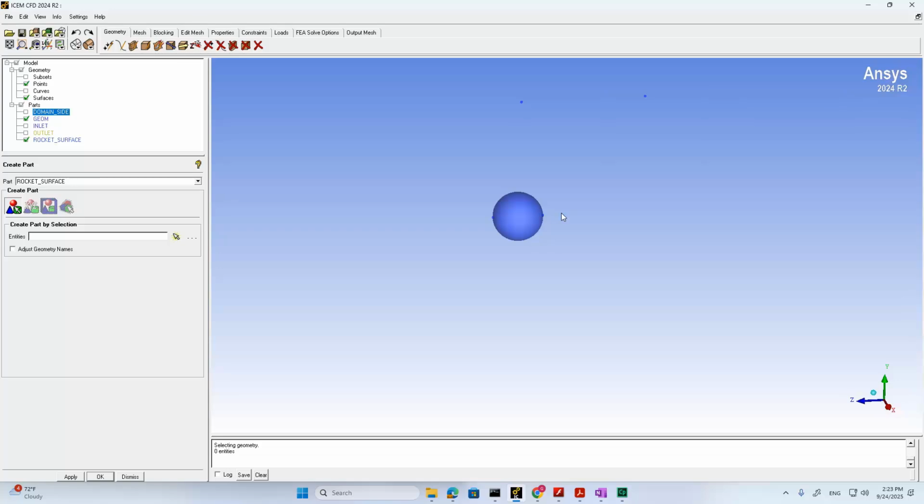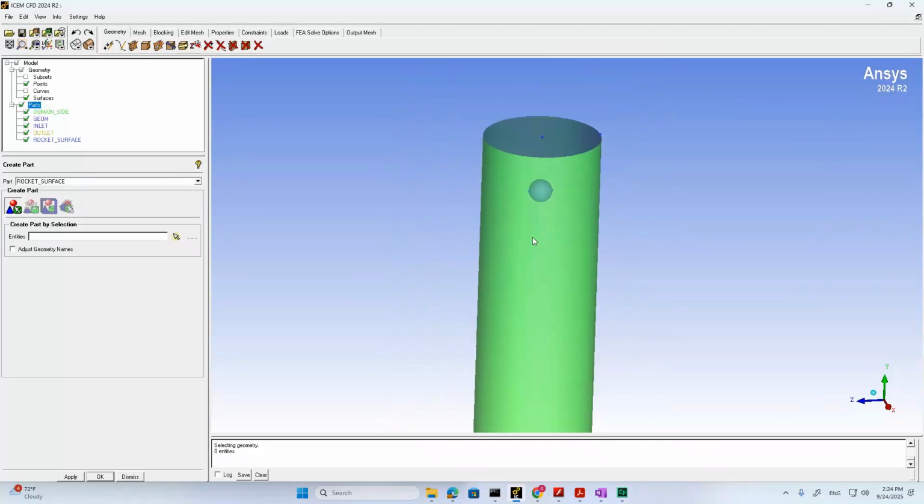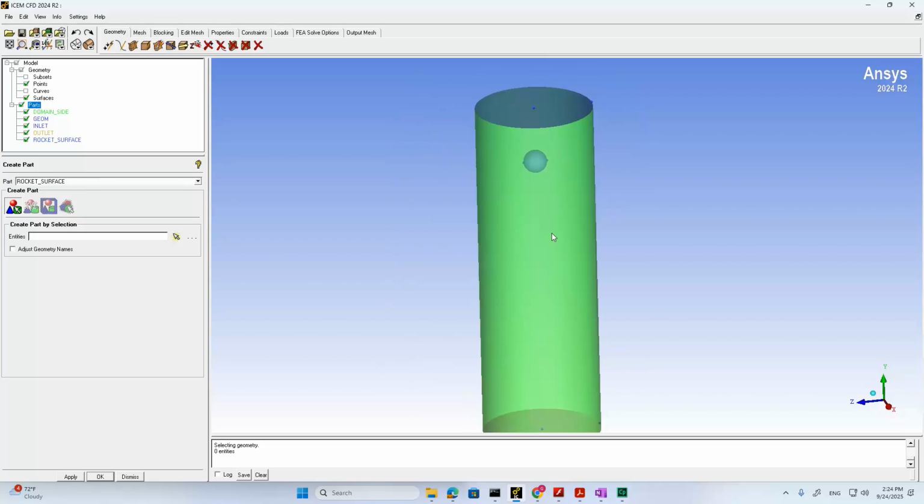So in that situation, you may want to define the air brake surface as one separate part. In this way, Fluent will be able to do calculations on that part to tell you how much drag force is on the brake. Now I have all my parts. Then I will go back to create my mesh.